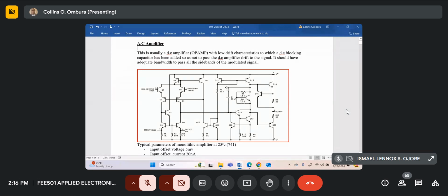T is temperature in Kelvin, B is the bandwidth, R is the resistance in ohms. And different resistances tend to generate different types of noises. So normally metal oxide resistances are the lowest noise resistances. So all this will be fabricated into an IC chip.